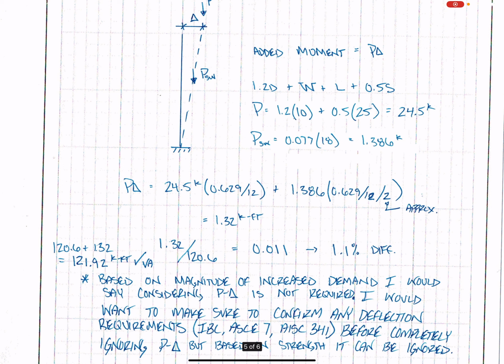I mean, I calculated. You would ideally use the shape function, though, right? Which is linear. Yeah, well, the way VA would be doing it is it would be doing its energy equivalent forces, right, and putting those forces out there at the nodes. So it would take half the load and put it all the way out there. Yeah, so have that self-weight already up there.